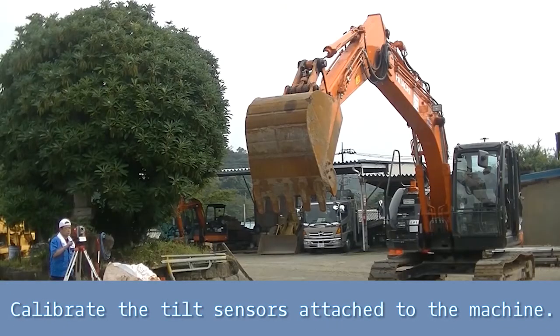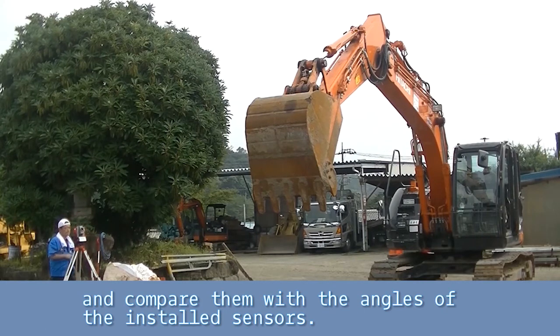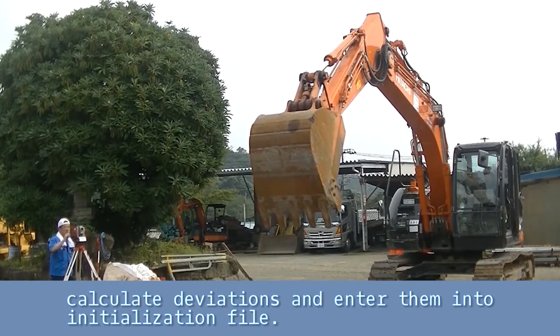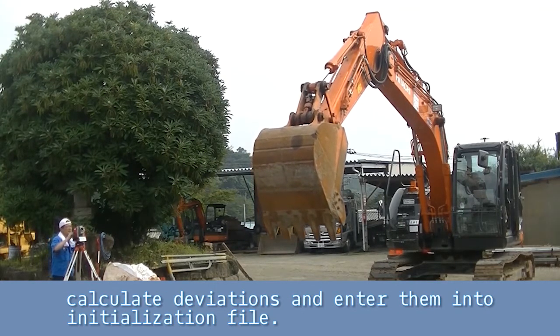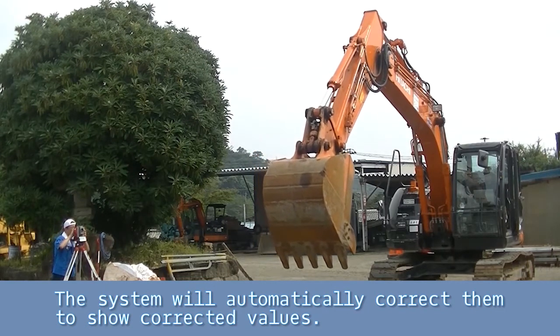Finally, calibrate the tilt sensors attached to the machine. Measure the angles between the arm, the bucket, and the boom with a total station and compare them with the angles of the installed sensors. From the measured and calculated angles between arm, boom, and bucket, calculate the deviations and enter them into the initialization file. The system will automatically correct them to show corrected values.